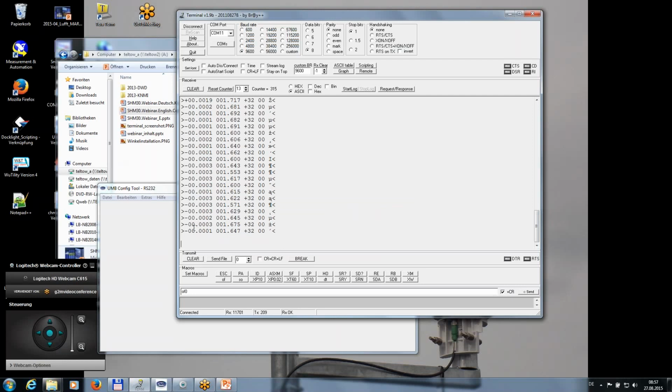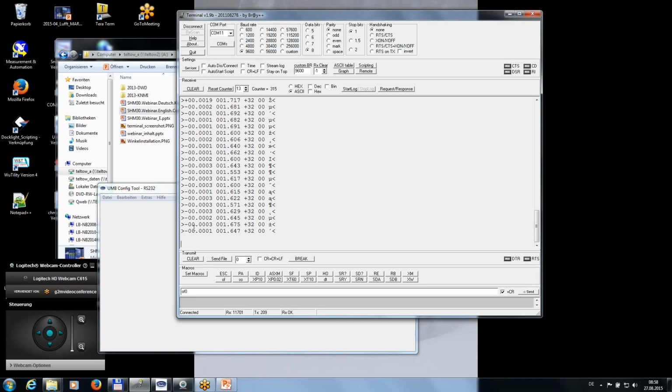So in the configuration of the laser snow depth sensor, you have these two values for the analog range. The values are RE and RB. RB is the beginning of the analog channel. I can stop my measurement again and ask the sensor now where it is.